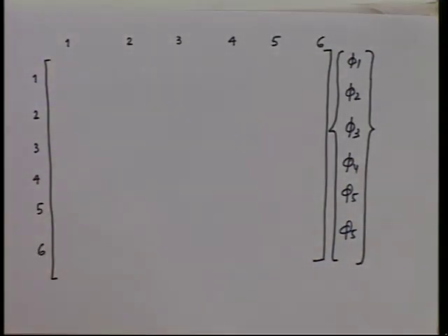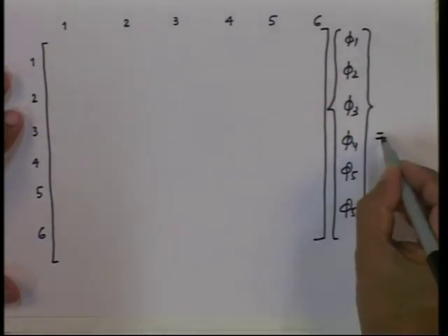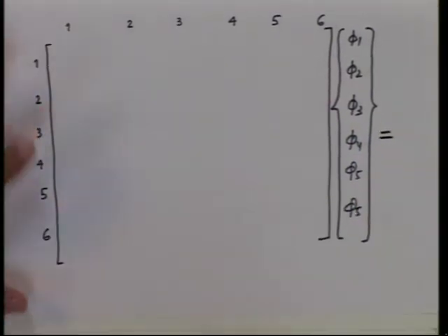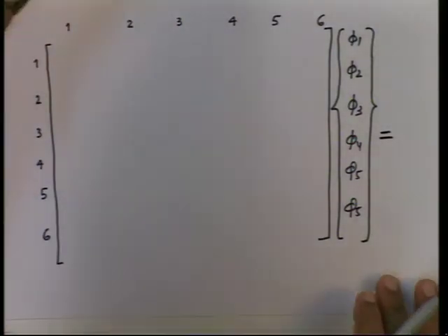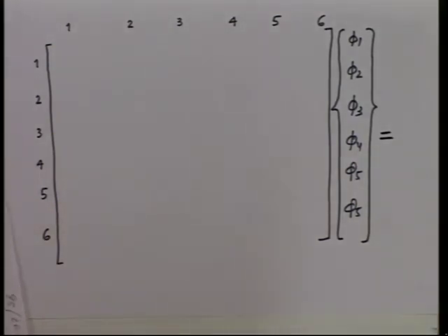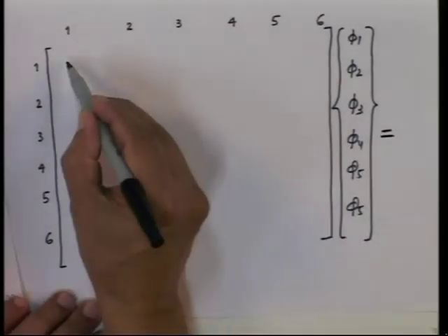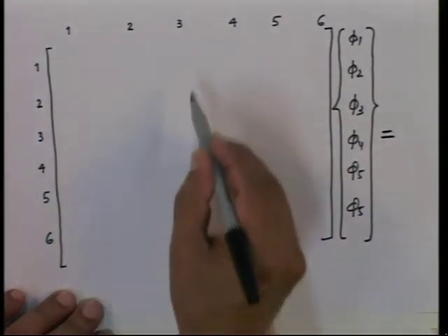That equal to, of course, the load, that I will write on the next page. So, let us first assemble the, that equal to the total right hand side, that is P. Now element 1, element 1 is 1, 2, 3. So, that means they will be confined in this 3 by 3, left hand 3 by 3.